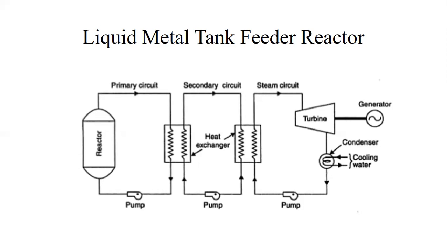The liquid sodium is discharged from the intermediate heat exchanger to the pool. It is then pumped upward through the core and re-enters the heat exchangers. In the other type, that is the pool type system or design of liquid metal fast breeder reactor, the intermediate heat exchanger is located outside the reactor vessel. The pool type configuration is widely used in the European and American countries.